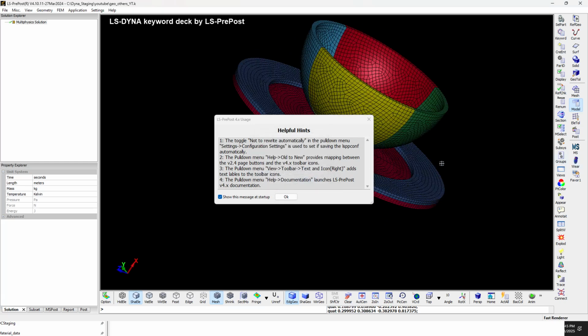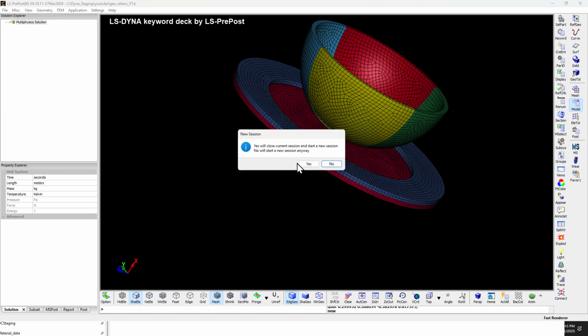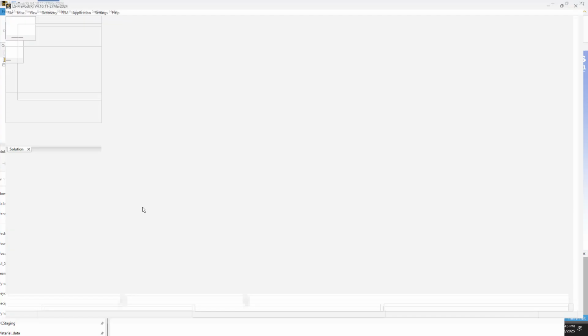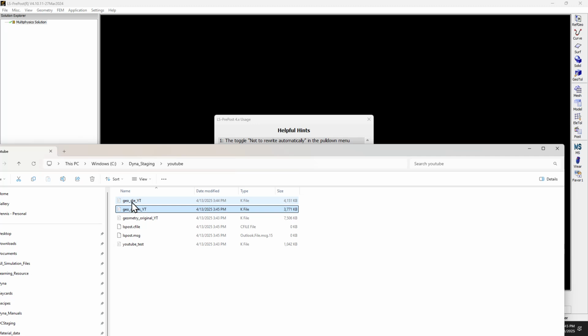Now remember what we're interested in doing in this model is to understand how the die itself wears over time, right? And this is why I'm separating them out, because all I care about is replacing this geo die file with the deformed shape from each stage of the analysis, so that I can analyze the progressive wear of a part every n cycles. In this case, n is equal to 10,000.